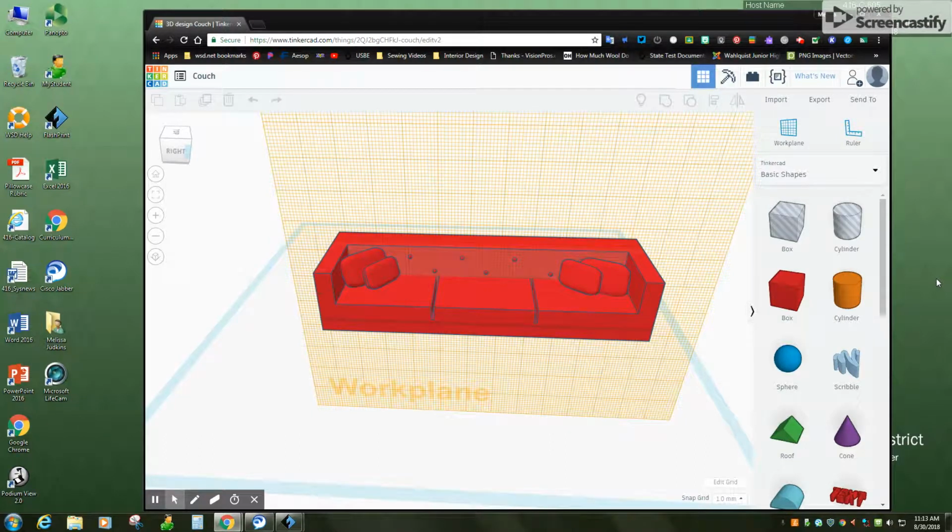In this, hopefully quick tutorial, I'm going to show you how to take an object that you've created either in Tinkercad or one that you've downloaded and export it so that it can be put into the right software that we use, which is called FlashPrint for the 3D printers. The FlashPrint software takes your object and slices it. It's called a slicer into the different layers so that the printer can print each layer.